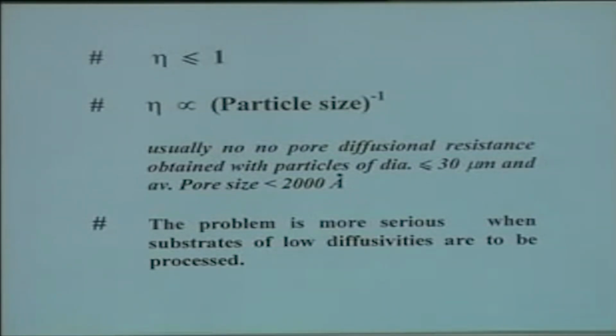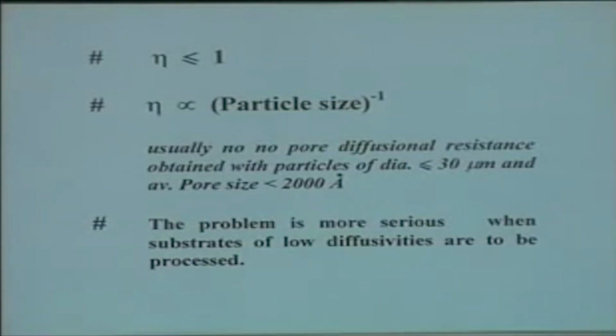Of course, as I mentioned earlier, two specific cases demonstrate where the effectiveness factor can be more than 1. One is in the case of enzyme reactions which are controlled by substrate inhibition kinetics. That means, at higher substrate concentration the reaction velocity is inhibited, therefore, as the substrate concentration gradient develops in the particle, the concentration drops and the reaction rate can be higher than at the surface, and therefore, the effectiveness factor can be more than 1.